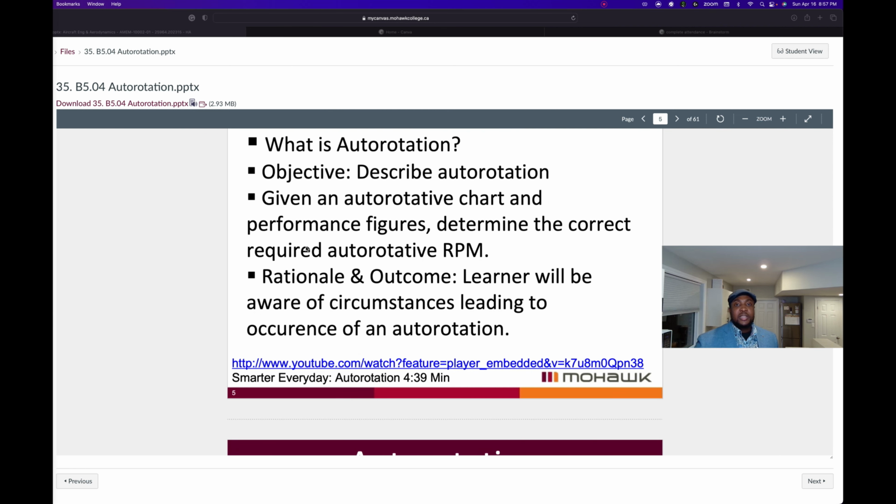From about 25% to about 70% of the rotor disc, if you were to divide it up, would be the driving region. And what did we say another name for the driving region is? We said it's known as the autorotative region. This is the region that produces a lot of the autorotative force. The innermost 25% is known as the stall region, and this region as well is a liability. And that summarizes autorotation.